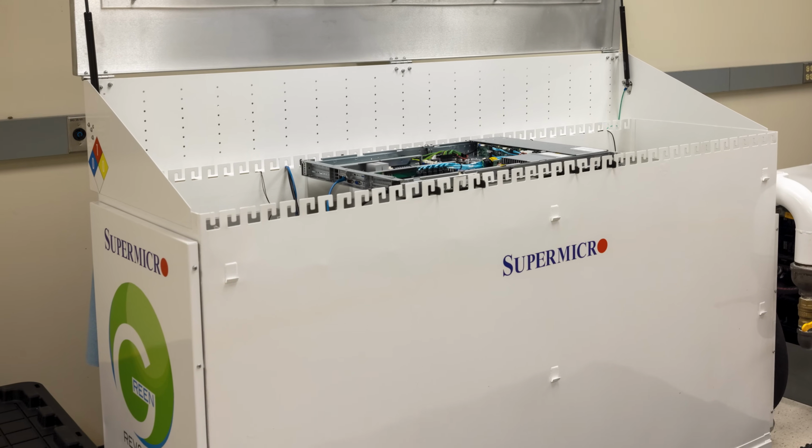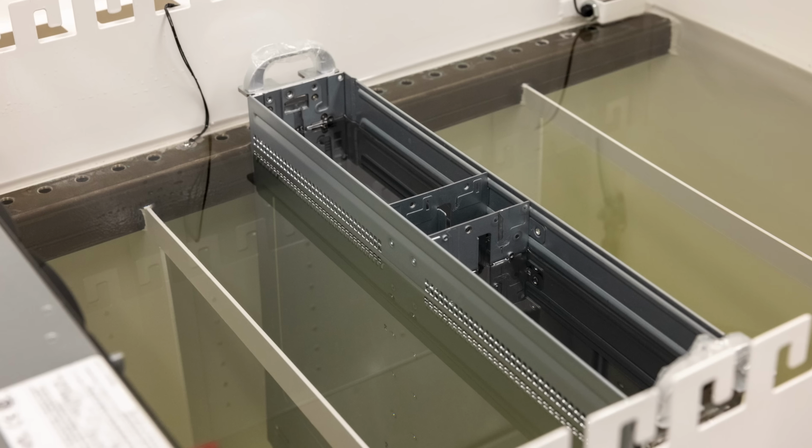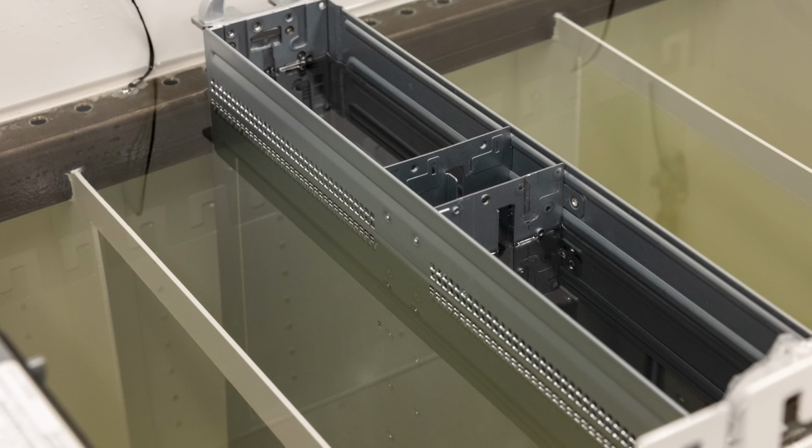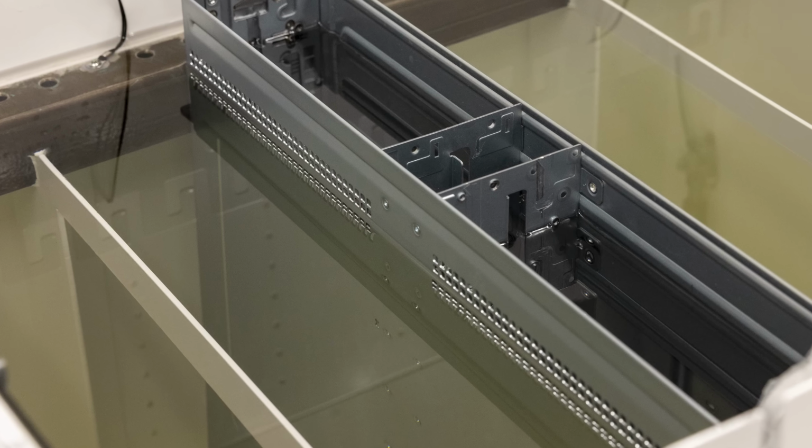Now, immersion cooling is kind of like the exact opposite. If you took the rear door heat exchanger as something that's relatively easy for your operations, you can integrate that very easily, but immersion cooling is absolutely a complete change to your data center and your operations. Instead of using vertical racks, you generally have horizontal bathtubs or tanks. Most people call them tanks, though I've heard them called bathtubs a couple times. The idea is that you have a giant vat of non-conductive fluid, and you take your server and dip it into that, and the heat exchange happens from the chips and all the components on your server directly into that fluid.